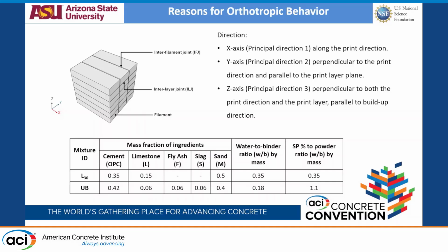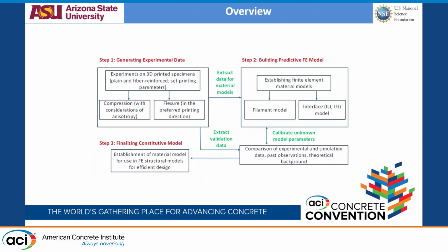While the water to binder ratio is different, like 0.35 and 0.18, we are doing the second mix to try to get higher strengths, in the range of 100 MPa, while the above mix is around the 70 MPa mix. So what is required to model all this?